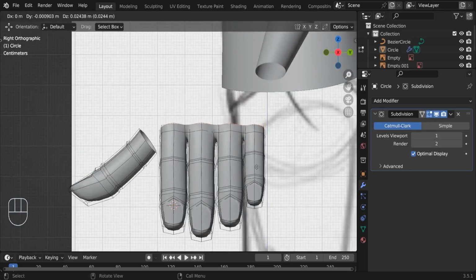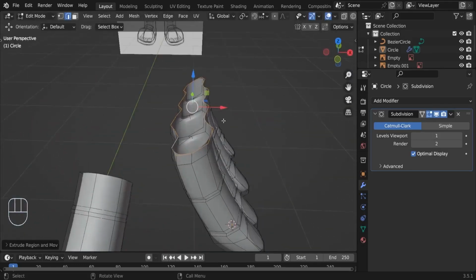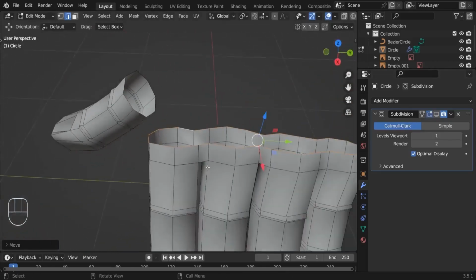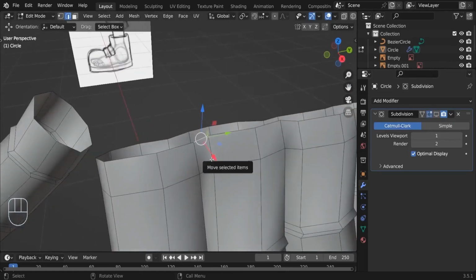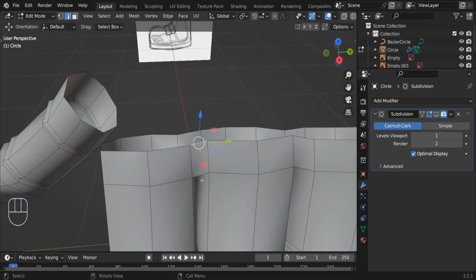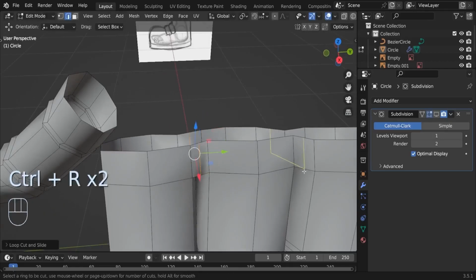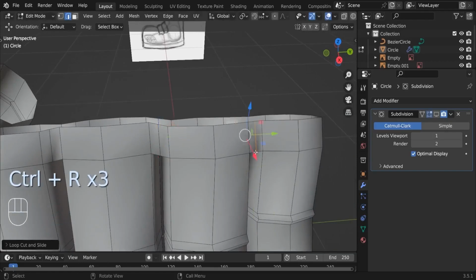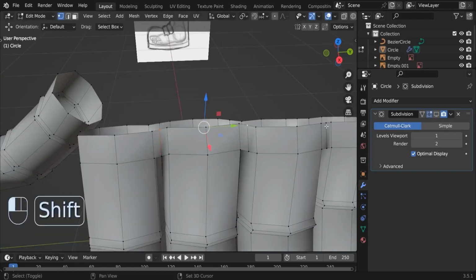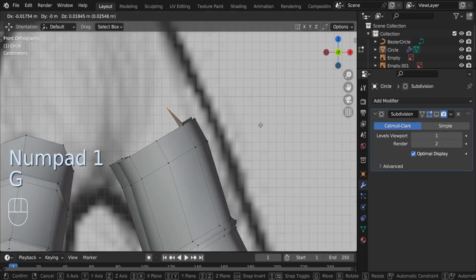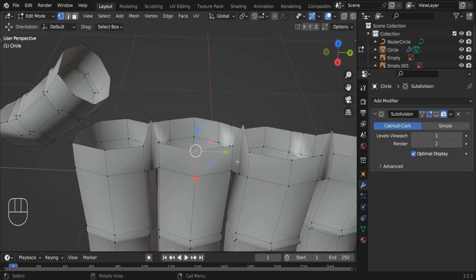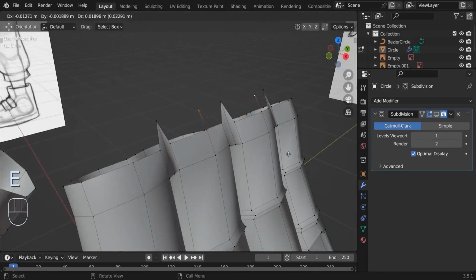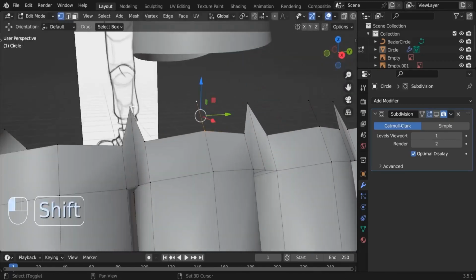You can extrude it, for example, here. And we gotta do something between. We can carry on. Let me just hide the subdivision surface modifier. So basically what I'd like to do, we can insert some edge loop here, Control R. So we can take these vertices, we can take them up like that. And let me show you. Here we can also extrude this part up. So this is a way of doing some optimization.